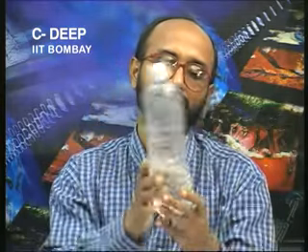We have seen the force acting on a horizontal plane, on a vertical plane, and also on an inclined plane. As far as fluid statics is concerned, when the force is acting on a curved surface, for example if you consider this bottle here, this side of the bottle is curved. When we have to determine the force on a curved surface like this, we have to take the horizontal component and the vertical component, and then determine the resultant force acting on the curved surface.